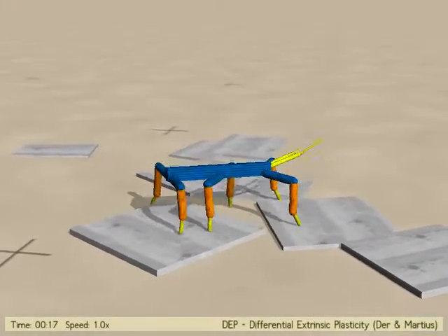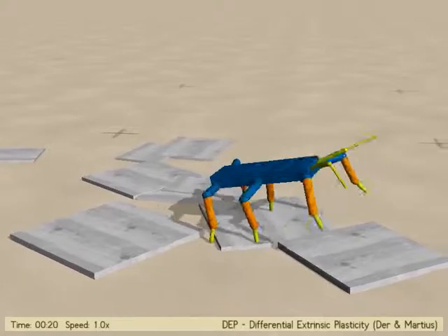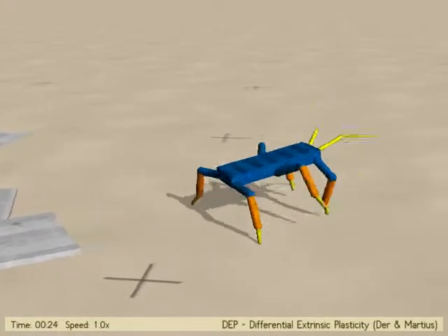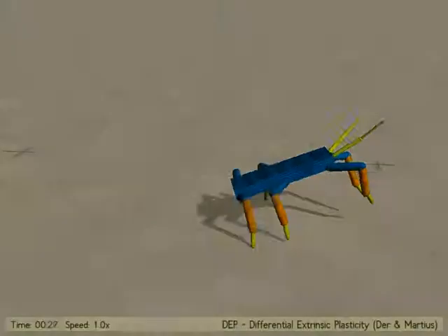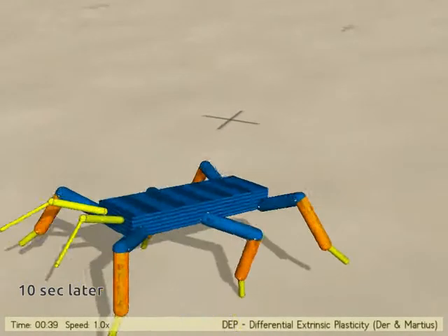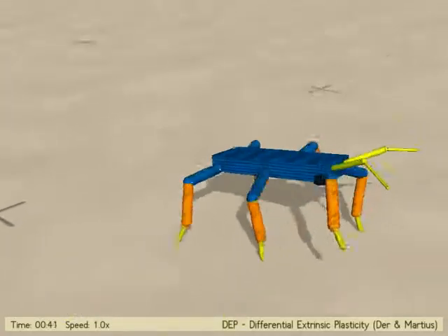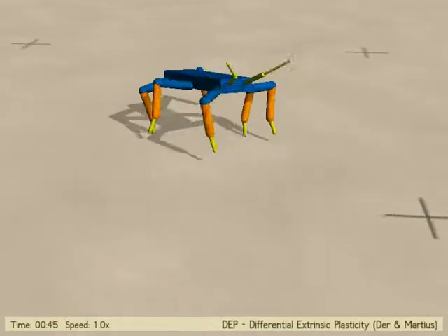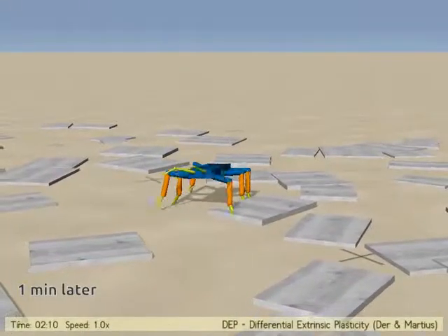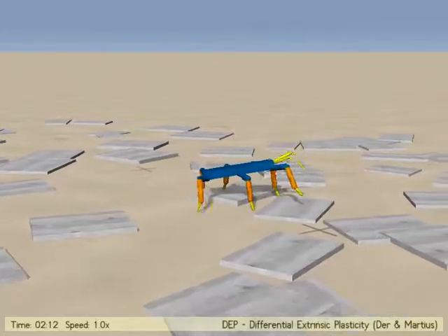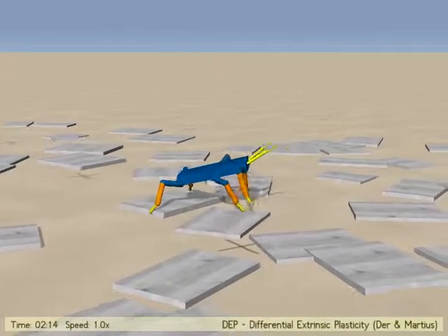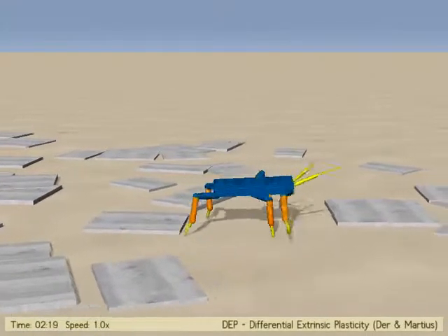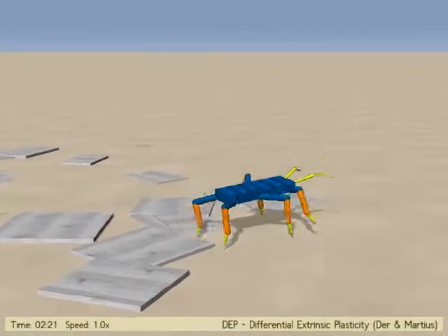Now we connect the same control network to a hexapod robot. After a very short time, we observe the emergence of the first locomotion gait, here a synchronous tripod gait. After this perturbation by stumbling with the front leg, the gait spontaneously transitions into a tripod gait. Everything happens online without any training. The synaptic plasticity is fast enough to react to different situations on the fly. When confronted with obstacles, the robot probes different motions, and here transitions into the first gait again.